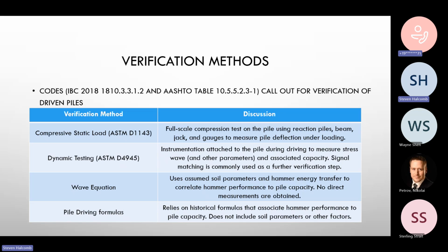And there are appropriate times to use that. You can't trust the blow counts in the material. If you're in ice or something like that, and the blow counts might be inflated, you don't want to trust the blow count to give you a capacity. So you look at the soil and what it should provide, and go according to that. But we mostly live in the dynamic verification camp, and there are four predominant ways to verify capacity.